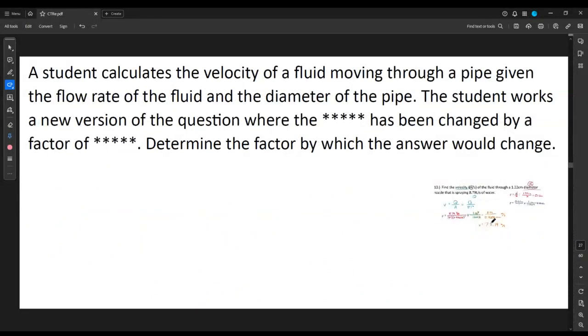Okay, then last one from that folder 3A material. Couple of little things to pay attention to. So our formula, we can probably reasonably skip to here. We know that typically if you're dealing with a nozzle or a hose or a pipe or something reasonably shaped, it's probably going to be a circle. You could have something that was a hexagon or triangle in a really horrendous question. I'm not going to do that to you. So what we're looking at then is the velocity is the flow rate divided by the area of the circle, so that's going to be pi r squared.